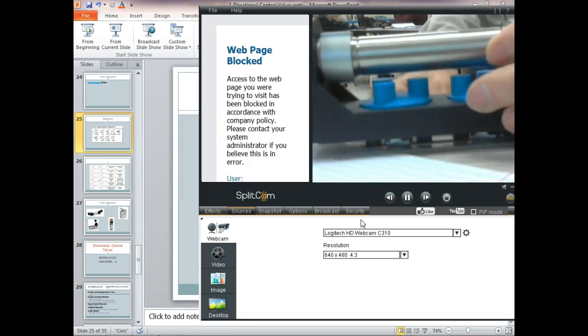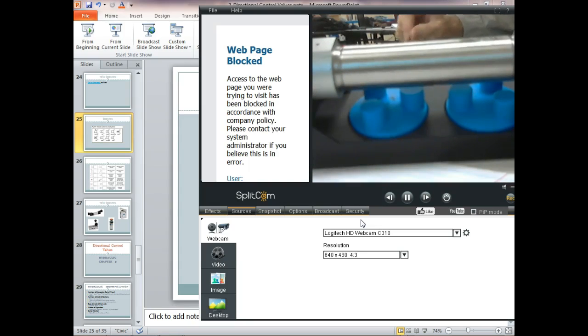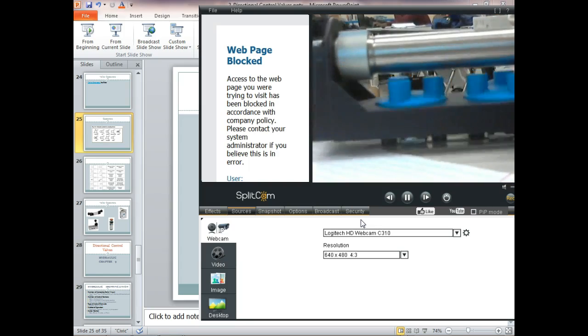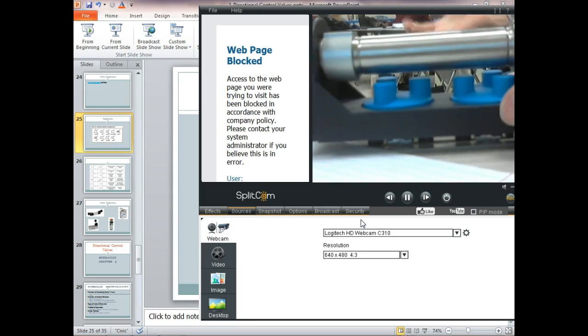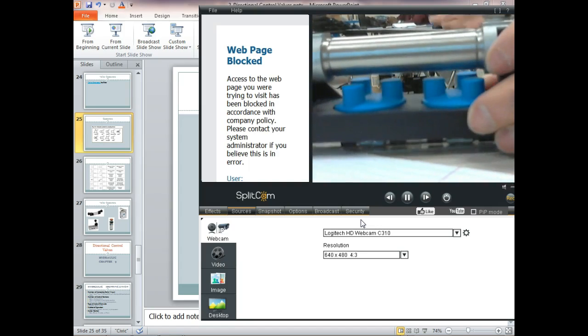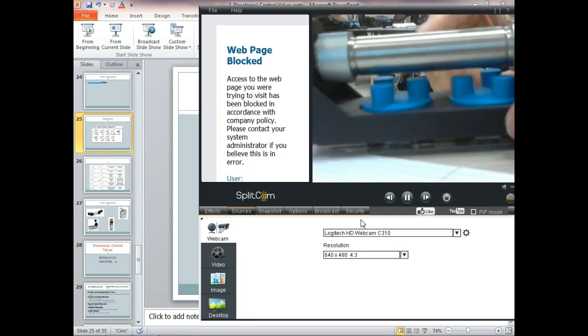This is our single acting cylinder. This is what we call a round cylinder. The problem with these round cylinders is they're basically non-repairable. They're cheaper, but they're non-repairable. We have another cylinder that they call an MFPA cylinder, and I'll show you some pictures of that, but it is a repairable cylinder. This guy right here is a round cylinder, and this is non-repairable. So if a seal goes out on this one, what would you do? Yeah, you'd throw it away because it's sealed up.